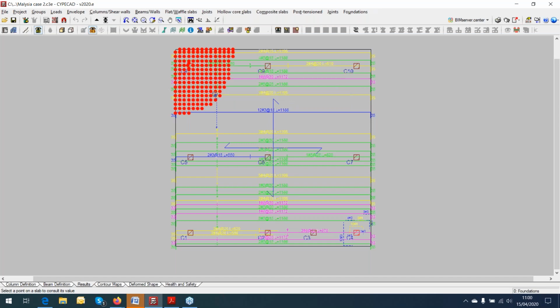But if you go inside, you will get something positive after the limit, which is going to be 2.23 millimeters. What is going to be the solution? The solution could be to increase the volume in this area, some mass, or give more load on top. There are different solutions, okay? But at least it gives you that modification.